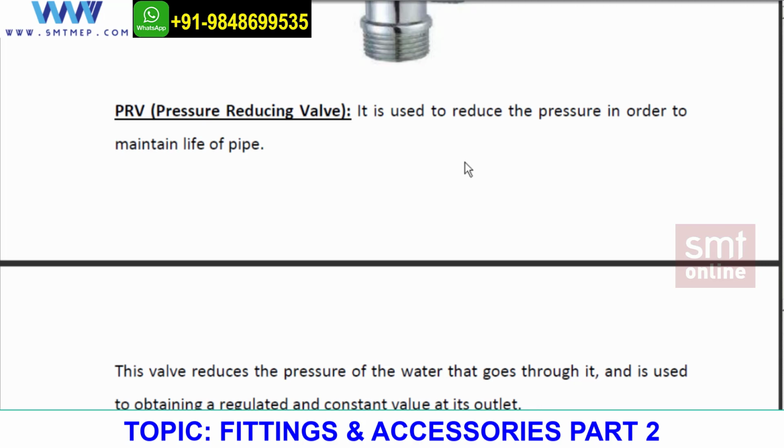Not only the fixture, because of excess pressure, what other things happen? Leakages will happen. For example, if I have done solvent welding, it will leak because of excess pressure, isn't it? So leakages might happen and water hammering will be there. We'll be discussing this later. Leakages, water hammering, and excess pressure will also reduce the life of the pipes,